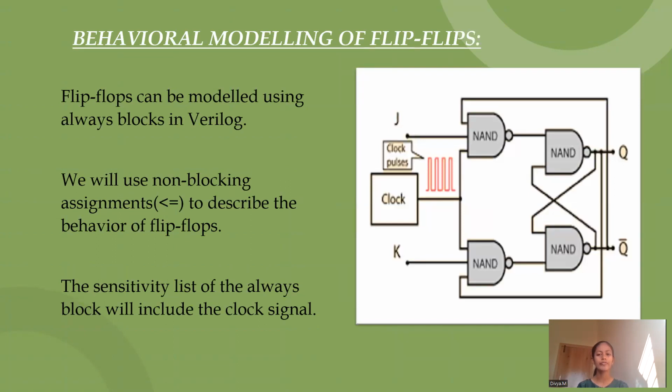Behavioral modeling of flip-flops. Flip-flops can be modeled using always blocks in Verilog. We will use non-blocking assignments to describe the behavior of flip-flops. The sensitivity list of the always block will include the clock signal.